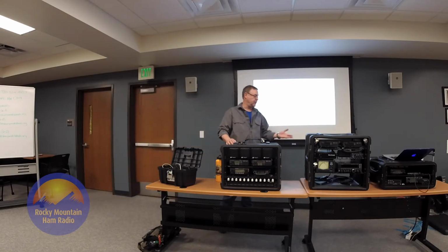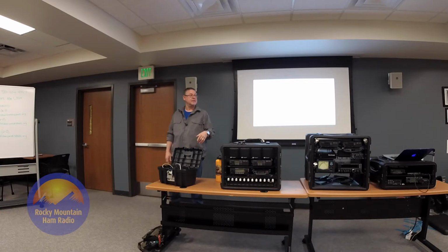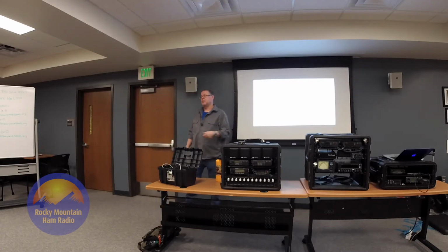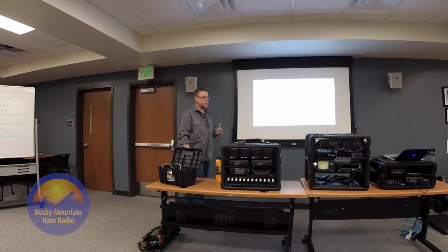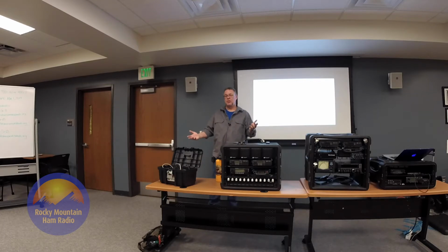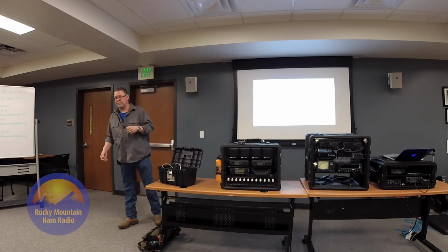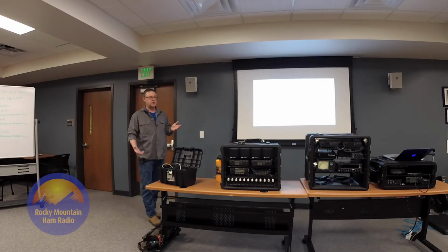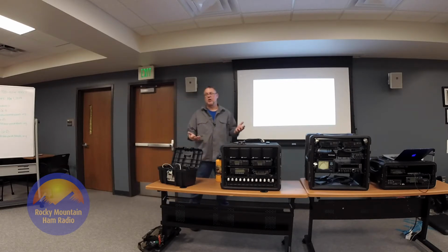You need a power cord, or cords to jump into 12 volts or whatever. So, tripods, antennas, cable. There you go, power cords, that's the main thing. Always carry power cords, or extension cords. Personally, I carry 100-foot number 12 wire. It's good for 20 amps continuous. You have very little voltage drop over the 100 feet, and they work good. And they cost about $90.